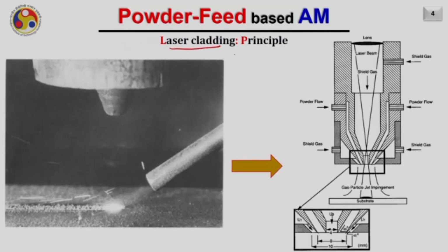As you know, laser cladding is the build process in powder feed additive manufacturing. Therefore, let us discuss a little bit more about this particular technique. Laser cladding, where it was invented, I have already mentioned, was something like this. It was shown by Professor William Steen, where there is a high power CO2 laser creating a molten pool, and from the side we are feeding the powder into the molten pool.